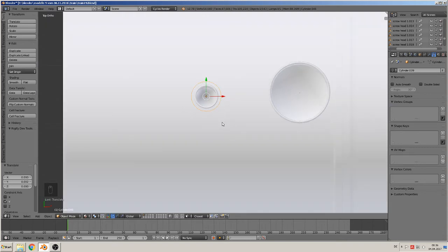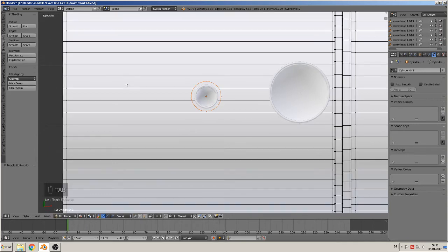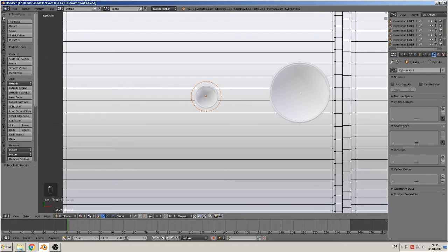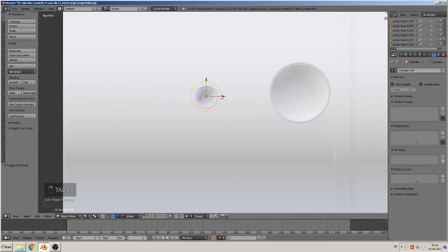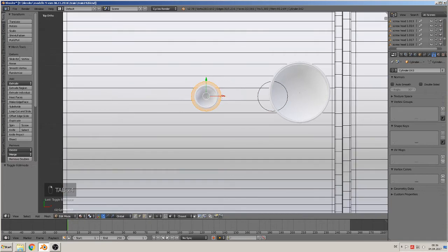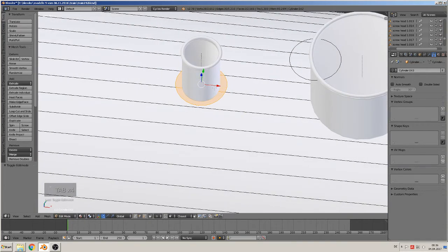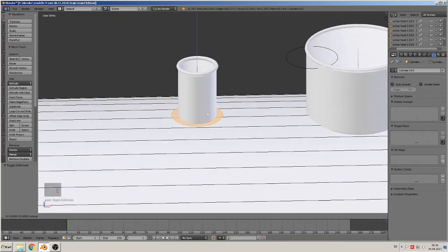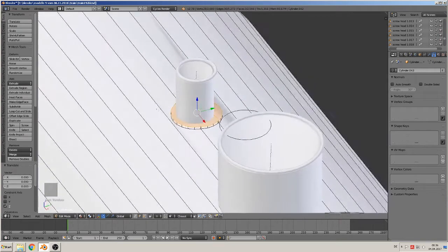So now we mark the whole thing and then edit mode, select all, and then we cut in this object. So now we can get them away and we see we have it here, and now we can extrude them out and then we have the correct one.